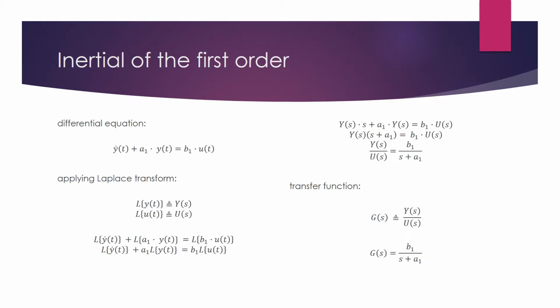First-order systems are also called first-order lags, exponential lags, or exponential stages. First-order systems are massless systems, which means that they do not exhibit the property of inertia. A good example of a first-order system is a thermometer. If a thermometer is initially at the temperature of 0 Fahrenheit and is suddenly thrust at time equals 0 into a constant temperature water bath held at a temperature of 100 Fahrenheit, heat will immediately begin to flow into the thermometer, and the temperature of the thermometer will begin to rise.